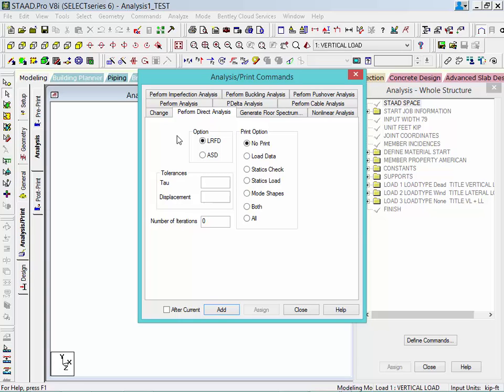This analysis is similar to a P-delta analysis with the use of the geometric stiffness and small delta options that can be selected. However, this analysis calculates modifications to the stiffness matrix using the tau factors described in the AISC 360.